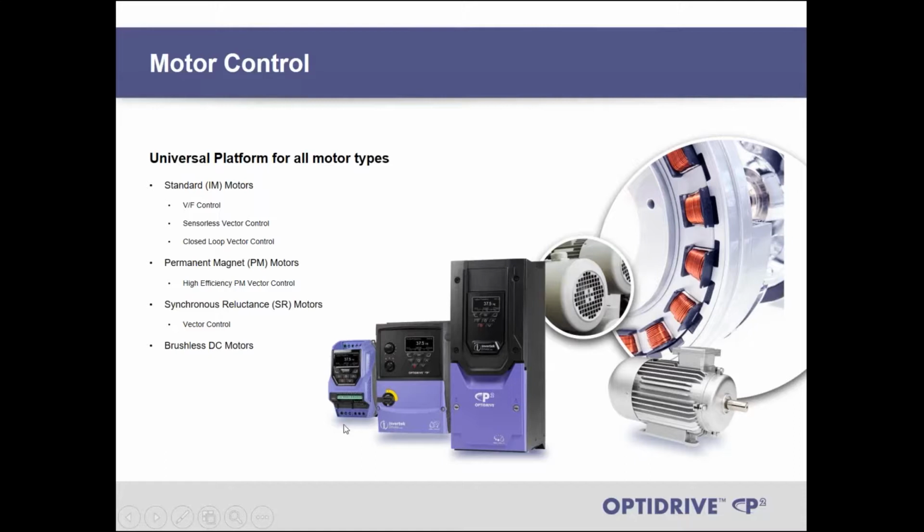an external module that you can insert, and this is an encoder module, so you can use the permanent magnet motors also with closed loop control. The A3 drives are only available for open loop control. So this can be particularly useful in more accurate, more precise applications where maybe you will need a more fine torque control.